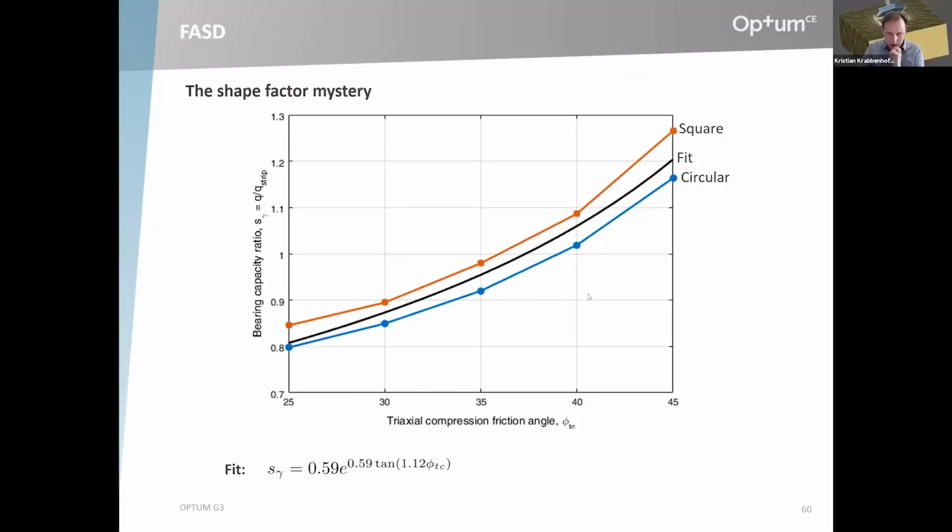Okay. Then there's an interesting comment that Lyamin et al., 2007, in a Géotechnique paper using discrete element modeling, also provide an expression for N gamma, and that gives values greater than 1.2 for phi greater than 45 degrees.